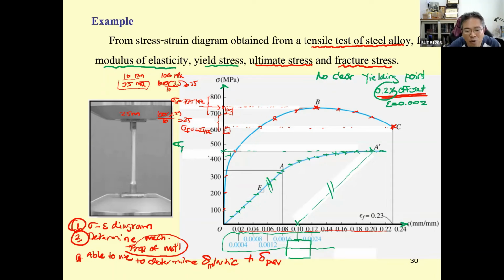And again, you have to measure this one. If you measure, let me put it at 5.5 millimeters, so this one is going to be 55 millimeters. Sigma sub y is going to be 55 megapascals. And then the last one, we are looking for the modulus of elasticity. The last point that we can use to determine this one is the proportional limit, and then E is going to be sigma sub PL